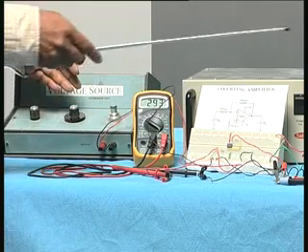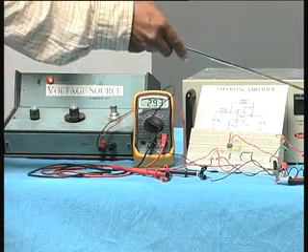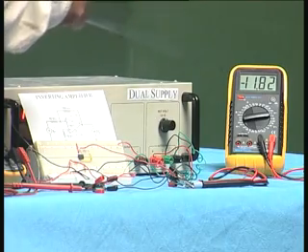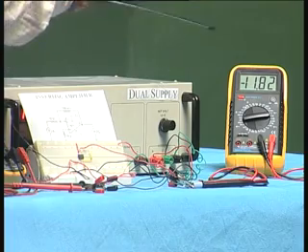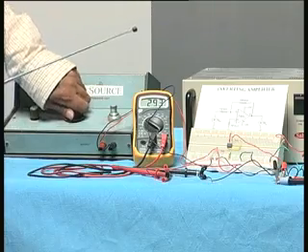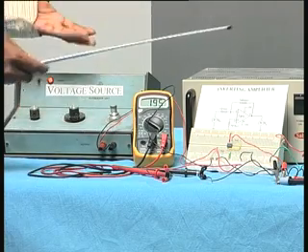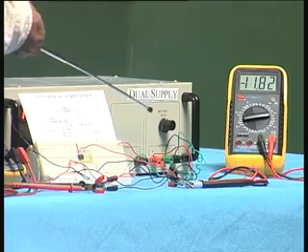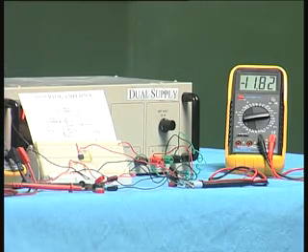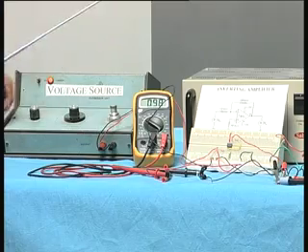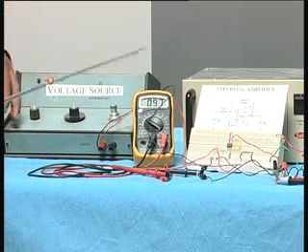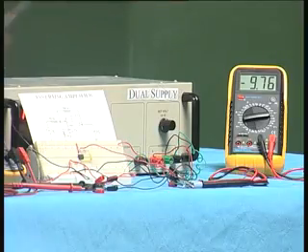If it exceeds the supply voltage, which is in this case plus or minus 12 volts, 11.8 is corresponding to the power supply voltage, minus 11.8, and therefore it has come to saturation. So if I come to 2 volts also, 20 volts cannot be shown because it is larger than 12 volts that I have applied to the op amp, so it only shows minus 11.82. If I come to 1 volt, then you see I am below the saturation limit, and therefore 1 multiplied by 10 you get 9.76.